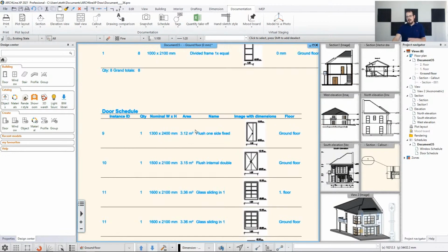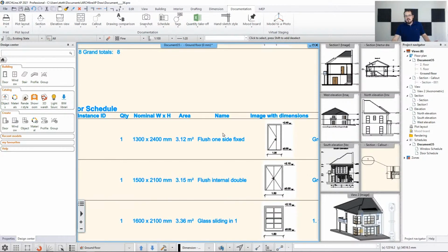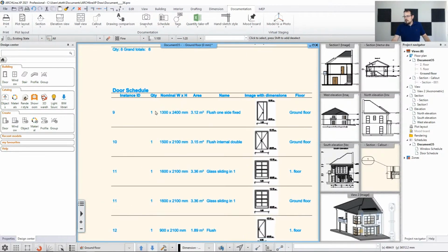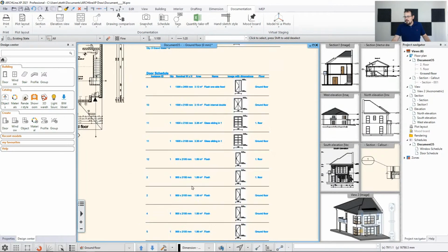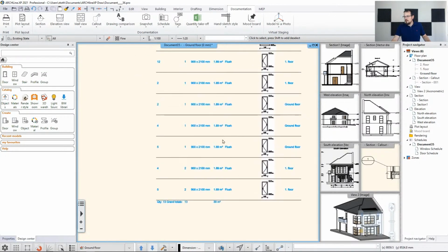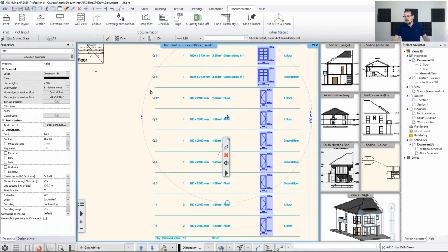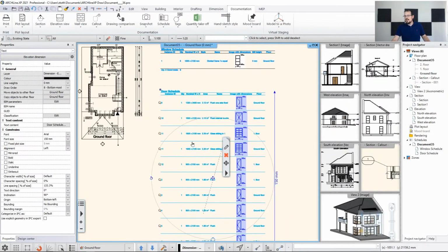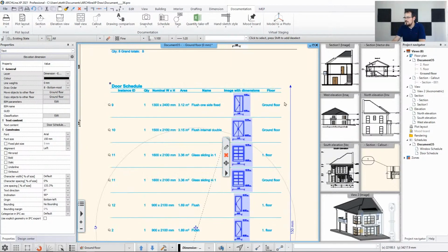Now, at the first glance, this looks the same way as my window schedules. But there's one vital difference. If you look for any of the elements which are individuals, maybe you have not two but only one of them, if you click on this list, you see that there's this magnifying glasses, and what they do is that if you click on it, they refer back to the original model. Let's illustrate that with, let's say, the entrance door.